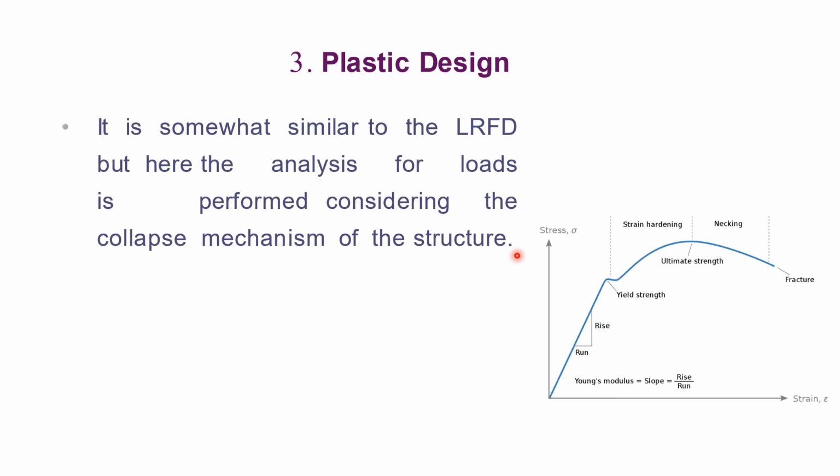Plastic design, that is the third design. It is somewhat similar to LRFD, but here the analysis for load is performed considering the collapse mechanism of the structure. That is the yield phenomenon after the load. When the load starts increasing in the steel members, then after the yield point the members start yielding, and the failure mechanism starts. But after the yielding, there is a margin of strength present beyond the yield point.